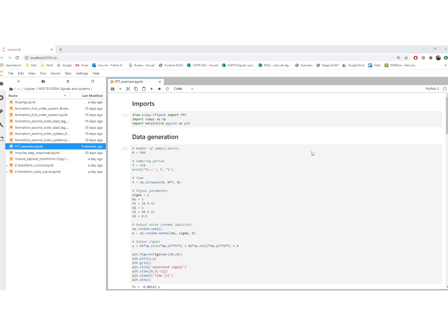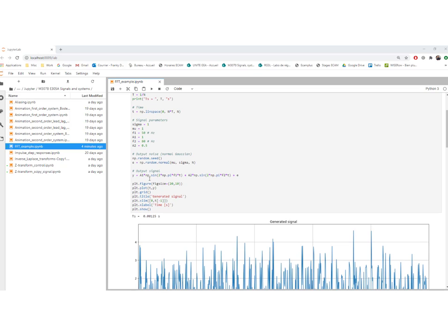So this example looks a lot like the example that we've considered in Matlab with the denoising. What we have here are two sines at different frequencies and amplitudes. They are given over here. The frequency of this one is 50 Hertz and this one 80 Hertz, and we add random noise here, and the particularity is that mu is equal to 1. So on average what is added here is 1 with a variance of 1.